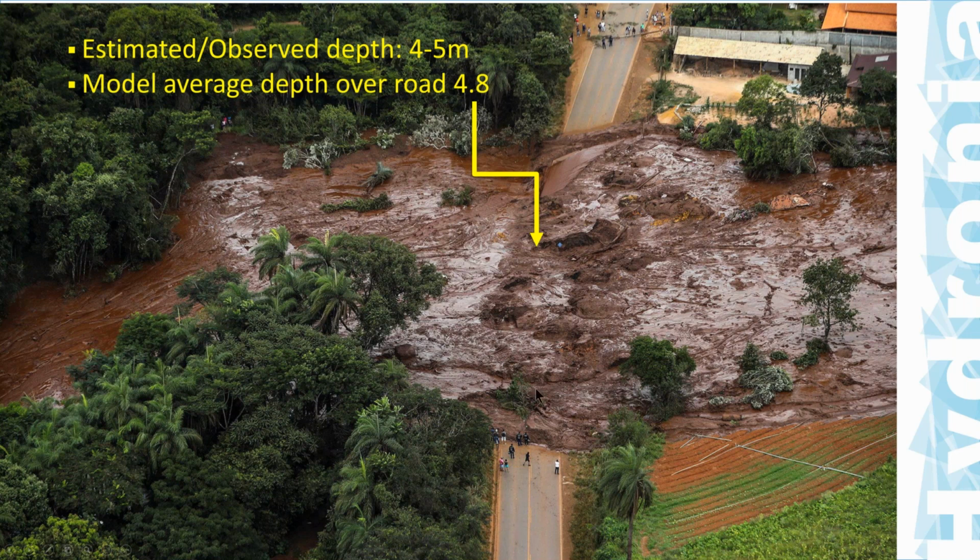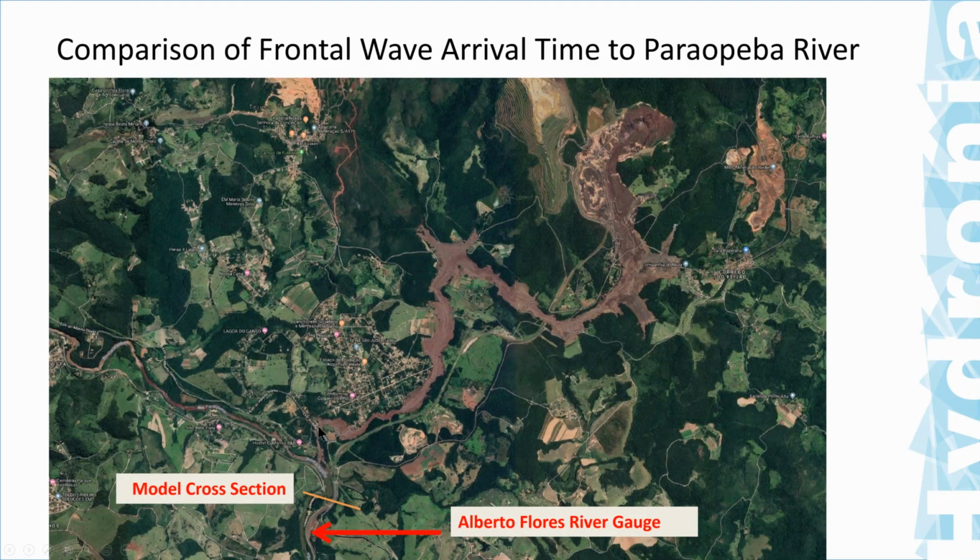And this is the Alberto Flores road, and in this case we have this image and we have people here, so we could estimate, and we have a house. So we did an optical approximation here to estimate the observed depth, and we found that this could be between 4 and 5 meters, and the average cross section here for the model results gave us an average depth of 4.8 meters. So it was pretty close to this, and this is a point that is several miles downstream from the dam itself. This is the Alberto Flores, so it's a little upstream from the Rio Paraopeba confluence downstream.